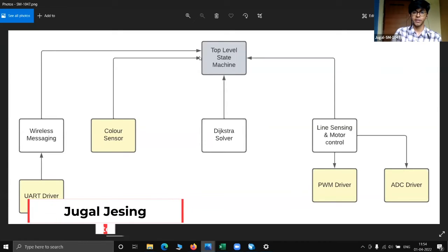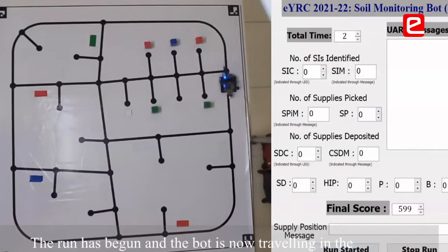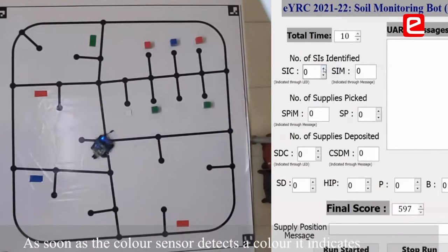I felt that I did not need an integrator, because of the way I constructed the line following code. I had a lot of if and else statements that were used to nudge the bot into the black line if it was straying away for too long. So I think that can't be called a traditional integrator, but it served the same purpose. So it reduced the steady state error.